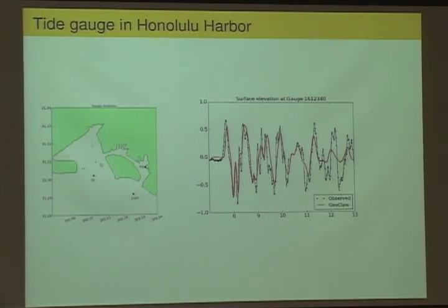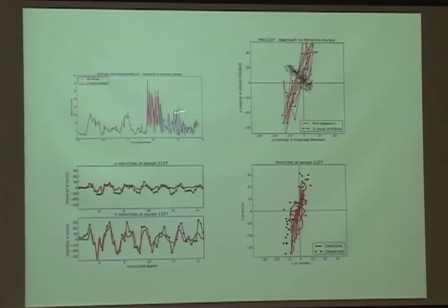If you think of this wave coming in, the surface elevation goes up and down pretty much equally over the scale of a harbor, say, but the currents could be very different. You could have strong eddies in some areas and other areas that are very still. And so if you start looking at something like the current velocities at particular points, it becomes much more sensitive. So this is the actual sort of data that came out of one of these current meters. And again, it was at several locations, but we depth averaged, since we're using depth averaged shallow water equations.